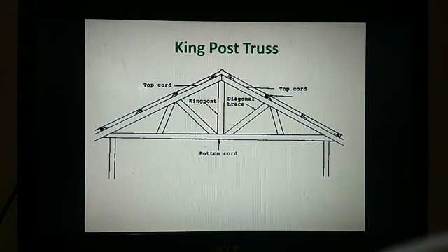So what are the general pitched roof trusses available? Let me show you the pictures. This is the king post truss. A king post truss is nothing but a pitched roof truss, which has a proper slope. Here you can see this is the top chord member, and these are the diagonal posts, which might be a tie member or a strut member. The center portion is called the king post, also called the center sag member.